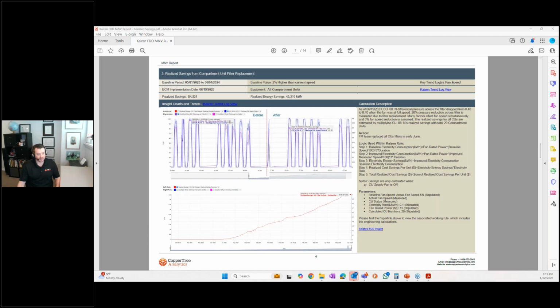So the last thing we will do is run air handling units at full throttle and then close all the dampers necessarily. That might be a test you want to do, but we might overpressure the ducts or whatever. So whatever safeties are built into the BAS, by the way, we are not touching, right? If there are safety mechanisms and thresholds implemented, and they should be, and they hopefully are, that's a good thing to test to or to know.